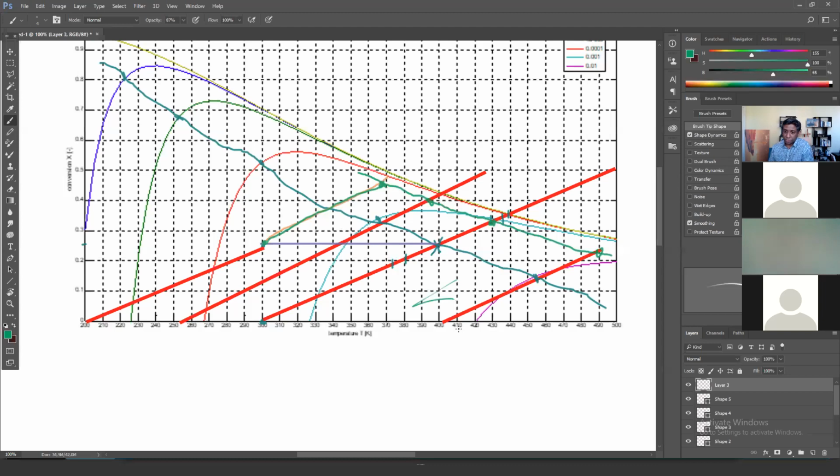Notice also, this is quite different to what we had with the CSTR, right? With the CSTR, we go boom from here, we go on there. The CSTR, it's from the inlet operation. This is totally inlet, right? It's 300 Kelvin, zero conversion. And then you enter the CSTR and it's instantaneously mixed, and it's a different temperature and a different conversion, right? So it's like a boom from here to there. That's what you see in the CSTR.